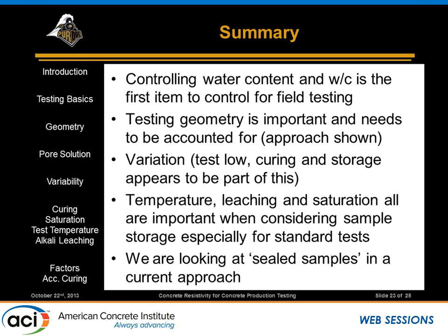Variation, all right, the testing can be low, but the curing and storage seems to be a huge part of this. All right, and right now the standard says you can store it in a wet room, you can store it in a bucket, all right, you can store it some other way.